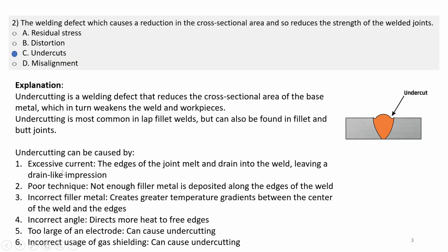Some of the causes for this type of defect are excessive current, poor technique, incorrect filler metal, incorrect angle, too large of an electrode, or incorrect usage of gas shielding.